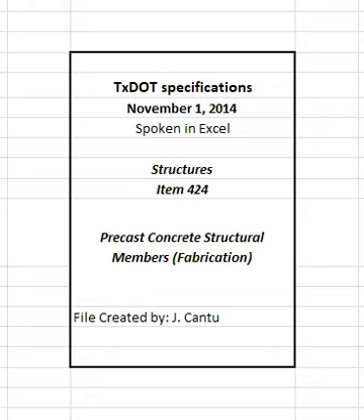Cover exposed concrete surfaces with polyethylene sheeting, burlap polyethylene sheeting, impervious paper, or other approved impermeable materials placed in close contact with concrete surfaces to keep them continuously wet. Provide additional moisture inside the enclosure in accordance with Section 424.4.2.7.1, Water curing, if this is not enough to keep exposed concrete surfaces continuously wet.